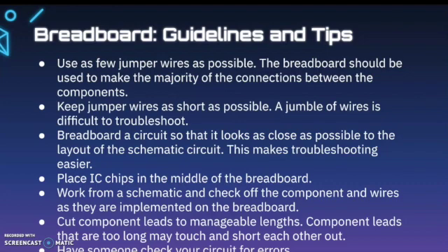Also, make sure you cut component leads to manageable lengths. Now, that's not an issue because we're doing this in a simulation, but when we get back to the classroom, we will need to make sure that we don't have a lot of wires sticking out, otherwise they can touch each other and short circuit.